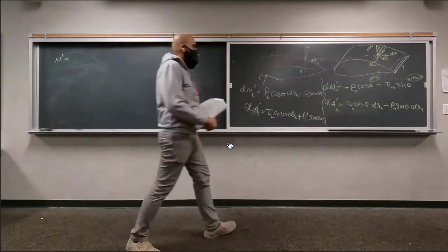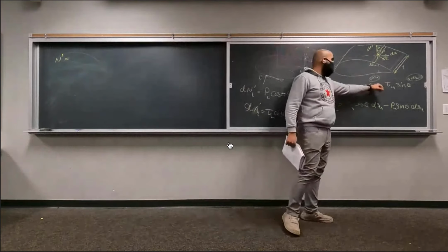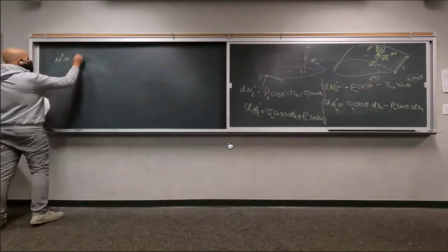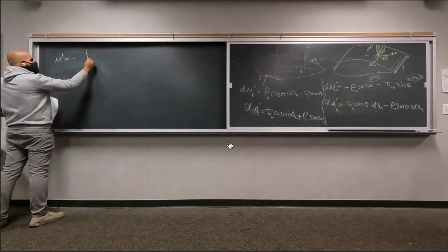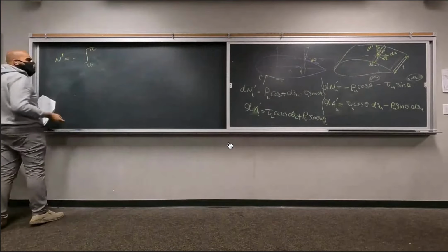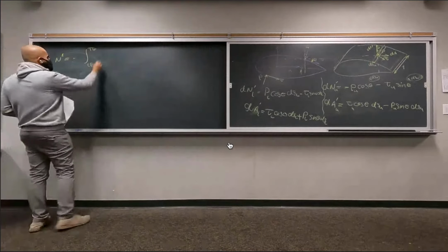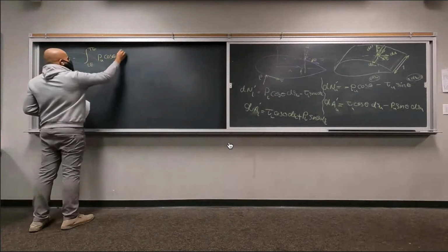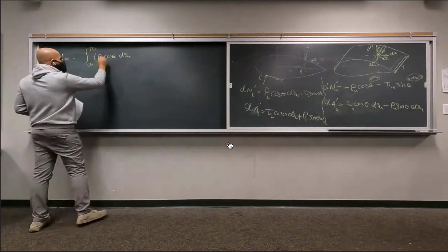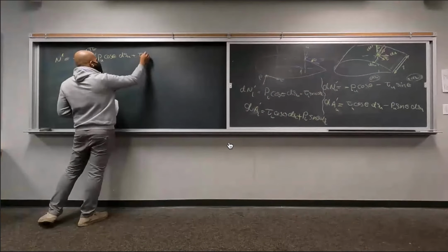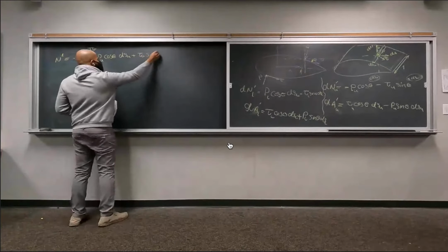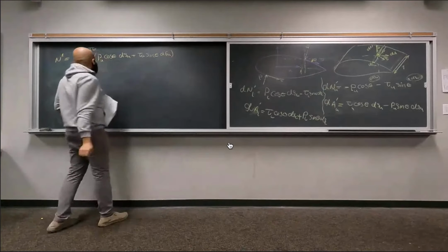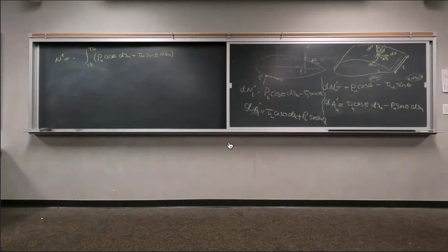So I can actually take the negative sign out here, out of the integral, right? We have two negative signs. So negative integral of leading edge to trailing edge, PU cosine theta dSU plus tau U sine theta dSU. This is the first part of the integral for N prime.